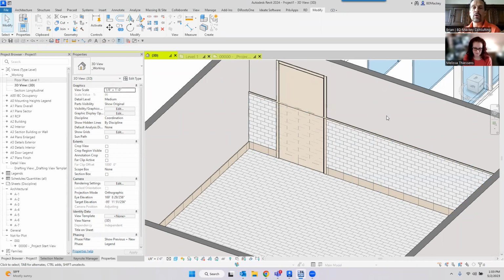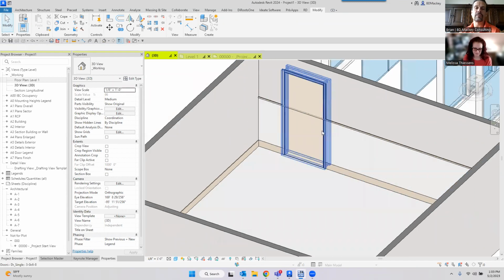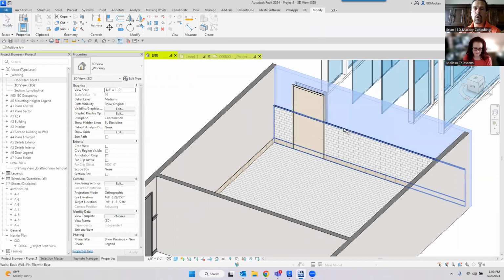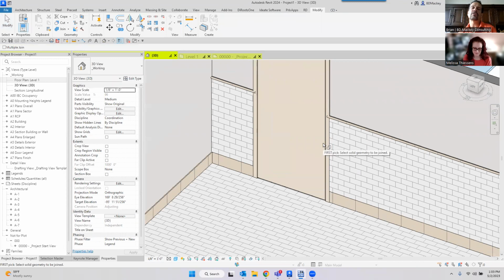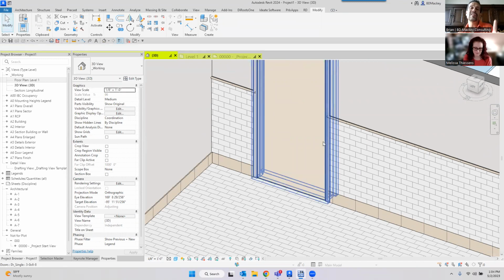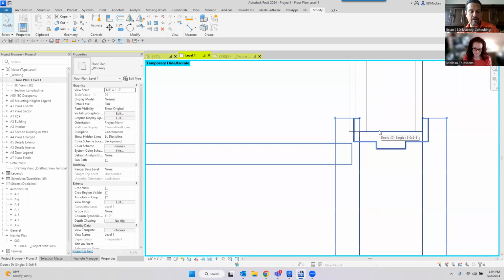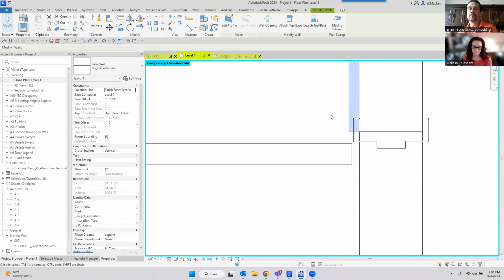So normally what you can do is model a wall in front of this, and that's all fine and dandy. Then you can use the join tool to join one wall to the other, and it will join the walls, and the opening will cut through that wall. So when I say the opening, inside that family, I'm going to go back to level 1, where I have the opening cutting the door, which happens to be along this line right here. It's cutting that finished tile wall right here, all right? That's fine and dandy for most tile walls that are thinner than the thickness of the door.